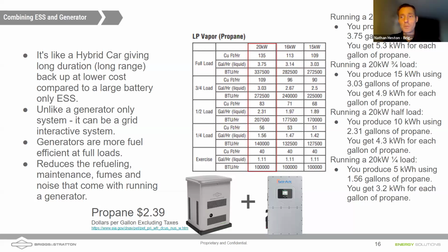I don't want to pollute the conversation more, but there's a big difference between AC coupled solar and DC coupled solar. When I bring solar strings directly into those orange and green cam lock ports on the Solarc, that's DC solar, and it can be on at the same time as the generator. It's just going to charge the battery. It's not going to cause problems with the generator. So I can use generator power, and if I just have weak DC solar, those two can complement each other at the same time. The challenge comes with AC coupled solar, which is when we already have inverters on the solar panels and they're kicking out 240 AC. Then we have to bring it through the gen port, and we don't want to have the generator on at the same time. So hopefully I clarified.